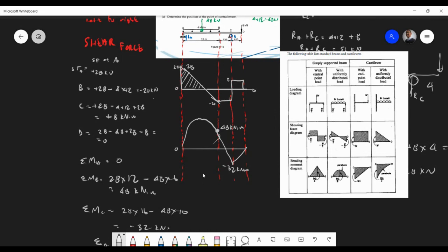But now we're not done yet because of the shear force being 0, which I mentioned to you. So this peak's supposed to line up here. So just give me a second. The bending moment's at the maximum, right? So it goes up like that. So make sure you get that done correctly. So now what we need to do is locate the position of where the maximum bending moment is. It's not 48, it's at that particular point.